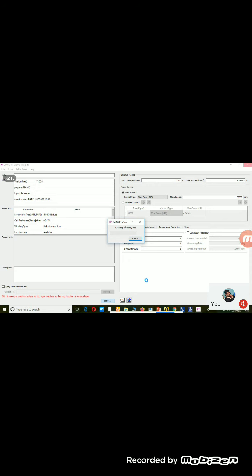So it is generating. It will take some 2 minutes to generate the efficiency graph, because the efficiency graph will be plotted across two parameters. One constant is torque, and the other can be anything. It can be speed, current, losses, or flux density. So among the three parameters, one is efficiency. That will be the common one, with a variation of two parameters, right?